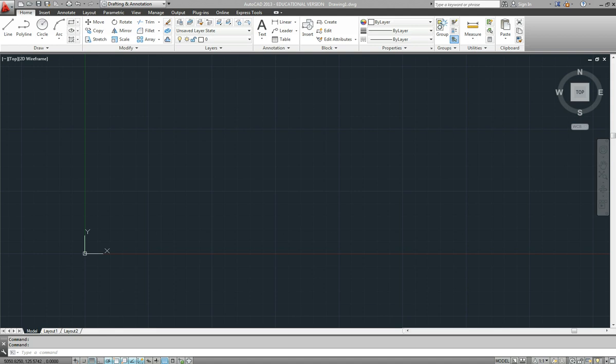So as we said previously, down in our bottom corner of the screen here we have a 0,0 point. And if we go into line drawing, rather than click to specify a point, we can actually type in the coordinates of the point. So if I type in 0,0, I can put in the z coordinate, comma 0 again, but I don't need that if I'm drawing in 2 dimensions.